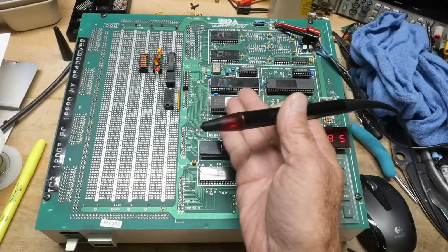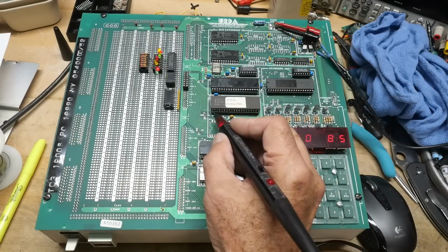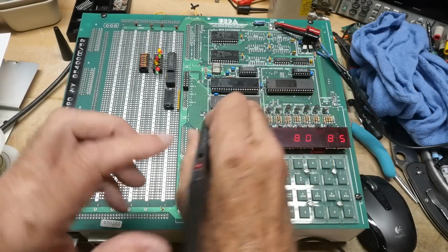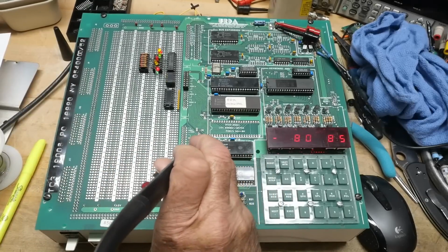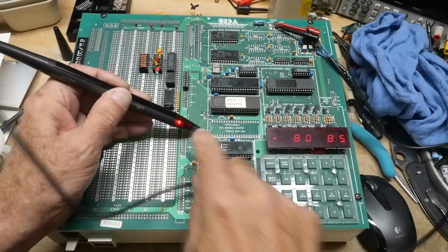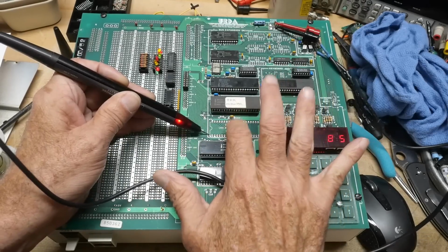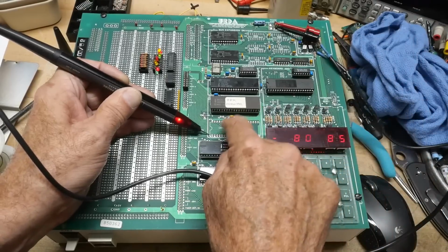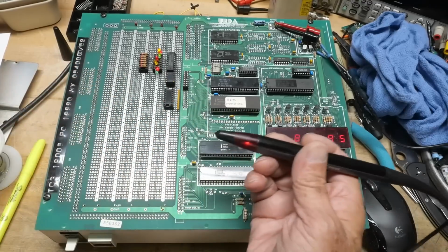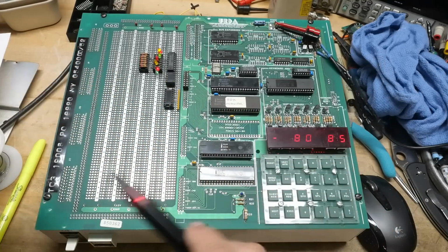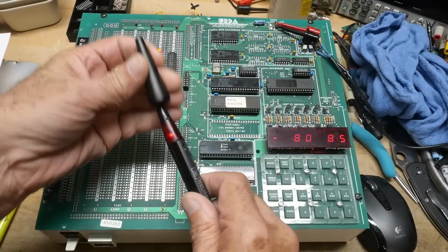Or you can say, okay, I have this chip, which is my ROM. This is the chip select, and I can see that my program's running because my chip select is oscillating. Well, here's an IC, and here's its chip select, and you can see that its chip select is always high, which means it's always deselected. So no part of the program ever tries to access this, right? And so you can get a lot done with just a logic probe, all right? But like I said, not many people have them these days. Raise your hand if that's gone inside your leg before.